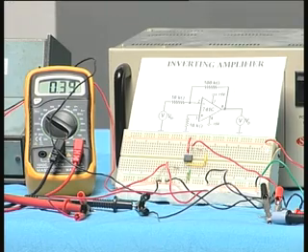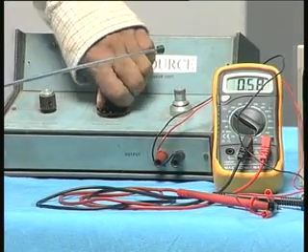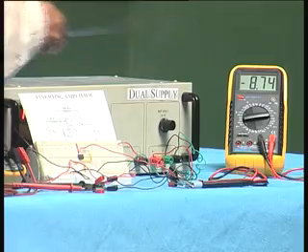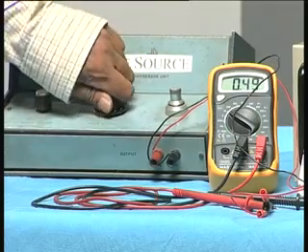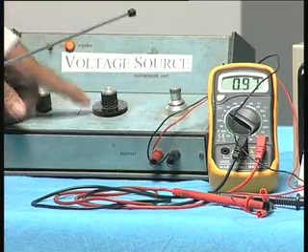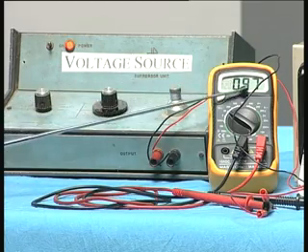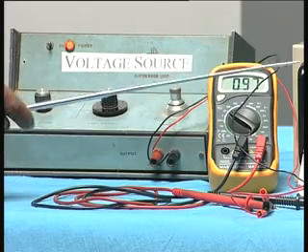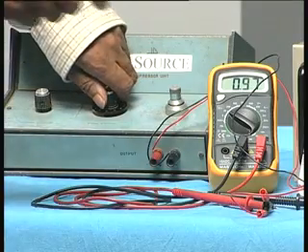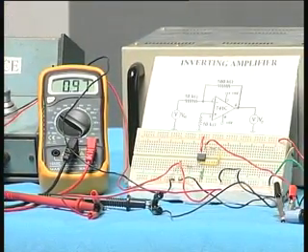Now if I keep on doing it, you might ask what will happen if I go to very high values. For example, now I apply 900 millivolt, you can see that 0.87 multiplied by 10 is 8.7. Now 8 volts I am getting, I will increase this still further to 1 volt at the input. So I have 1 volt here, so you have 0.97 volts here, correspondingly. So multiplied by 10 is 9.7 volts, that is what you are getting. Now if I put here 2 volts, what will you get at the output? Obviously you will say 2 into 10 should be 20 volts. Let us see whether we get 20 volts.